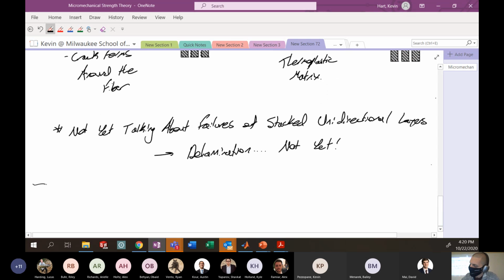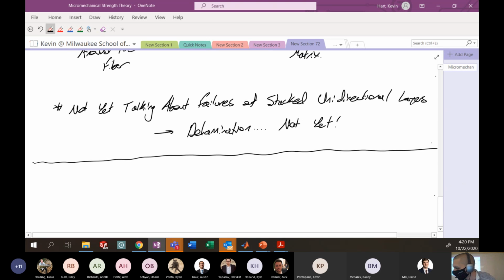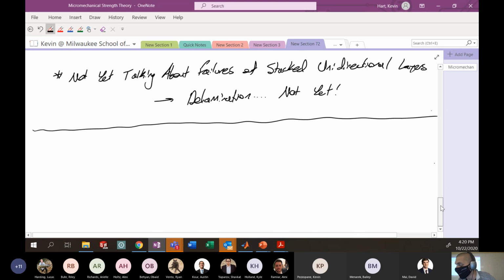All right. So just kind of physically, you're going to see failures that are just different than what you might see from traditional materials, just because you have two materials in one, right? A composite, physically distinct materials. So you could have failure of component A, you could have failure of component B, you could have failure of the interface between those two things. And it's sort of unique to composites in the way that they're going to fail relative to what you might think about failure for just general isotropic materials.